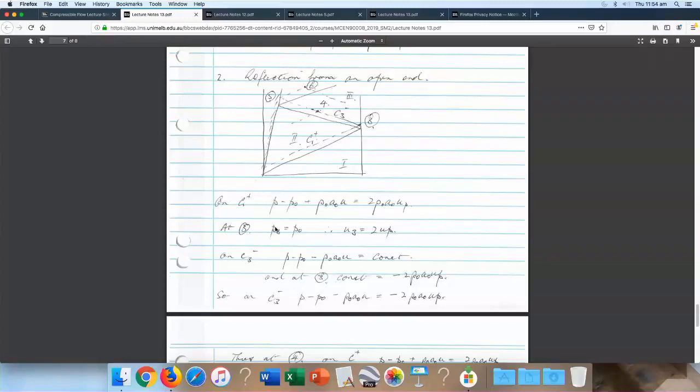But if it diverges in a supersonic flow, it accelerates. So that's obviously incompatible. The only way you can have a decelerating flow that's expanding in area is if it's subsonic. So you have to go through a normal shock.